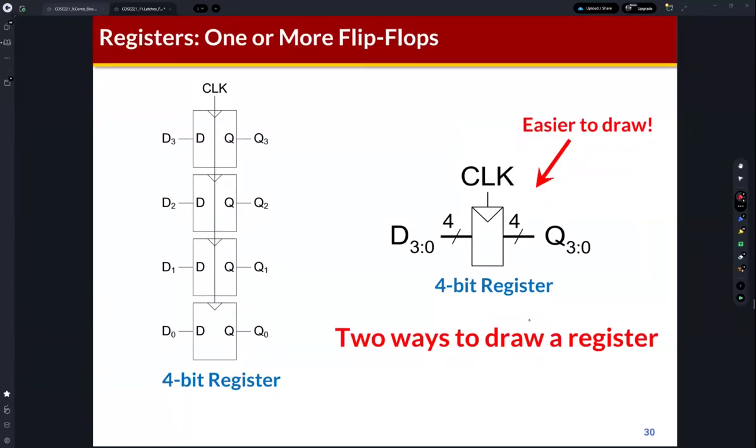As I mentioned, in digital systems we frequently use flip-flops. So we can also use some vector, like a group of flip-flops. As you can see, this is the D input, but the width of this D is 4-bit. Okay, it's a 4-bit signal. Then we can implement the flip-flop like this. Because Q is just equivalent to D, the bit width of Q is 4-bit. Then you can simply write flip-flops like this.